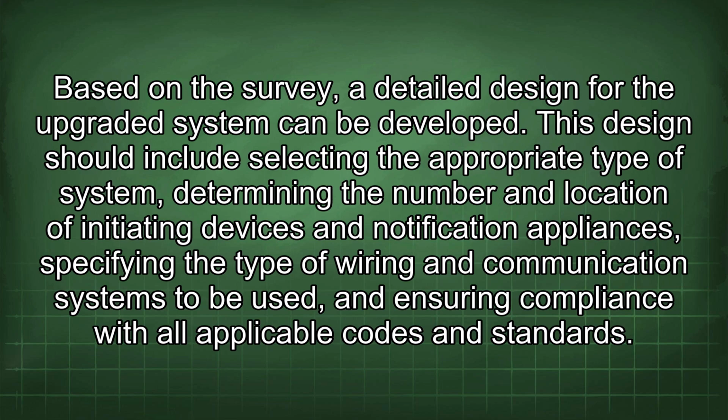Based on the survey, a detailed design for the upgraded system can be developed. This design should include selecting the appropriate type of system, determining the number and location of initiating devices and notification appliances, specifying the type of wiring and communication systems to be used, and ensuring compliance with all applicable codes and standards.